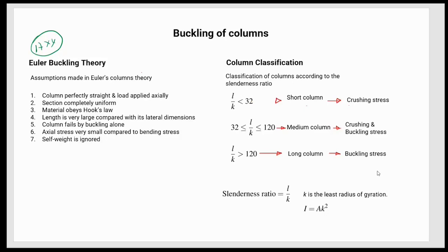So what would be the failure mechanism of the column, for example? If it's a short column, you need to be concerned with crushing stresses.